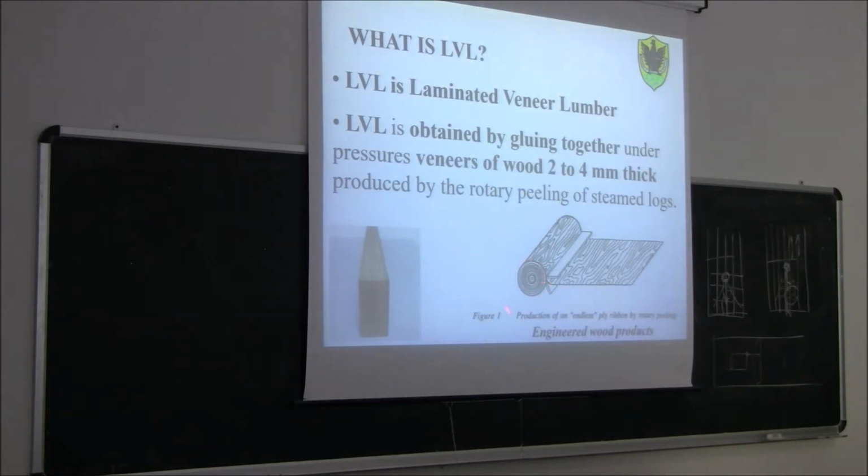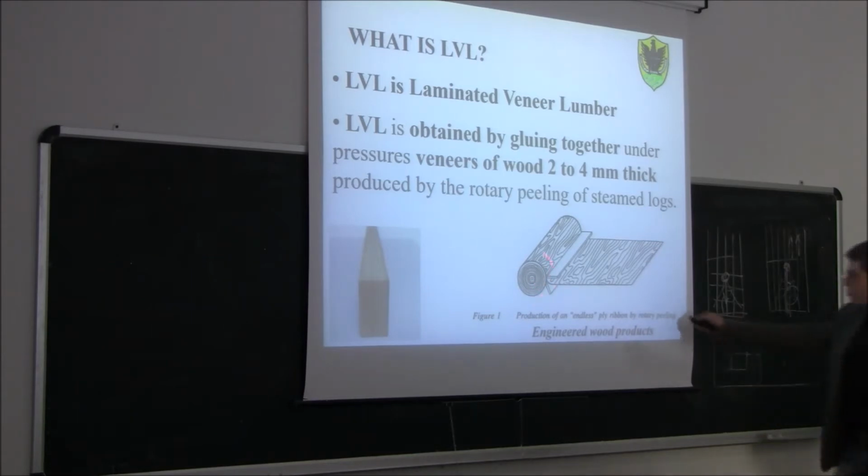After that, you see this one. It is rotary peeling. So the whole trunk is rotary peeled. Here we have a shape, and there is another machine making this spin. So this one is going to spin this way, very fast. And there is a blade here. So in about 10 seconds, this log is transformed into an endless veneer. Exactly like the comparison we made last time with toilet paper. You make it run, and then you get this endless veneer.